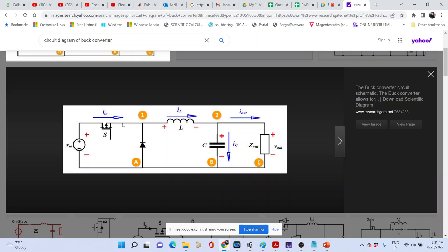Okay, sir. So VGS, how do you turn on? By controlling VGS. Yes. You need to apply a voltage, say plus 10 volt or plus 5 volt, whatever voltage you are giving, with respect to this potential, on which my cursor is right now. With respect to this point, you need to apply 10 volt or 15 volt, whatever voltage it is. You need to apply a positive pulse with respect to this point.